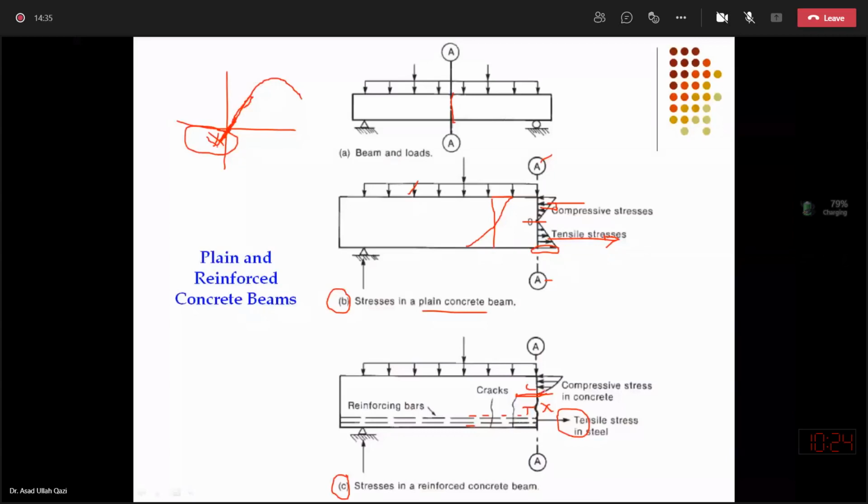If I further apply load, I may approach the maximum strength of the concrete, the peak. And if I further increase the load, I may enter the softening domain, and eventually when it softens to 85% of its peak, 0.85 of the compressive strength, we will declare that this is the crushing strength of the concrete, and now concrete can't take any more stress.